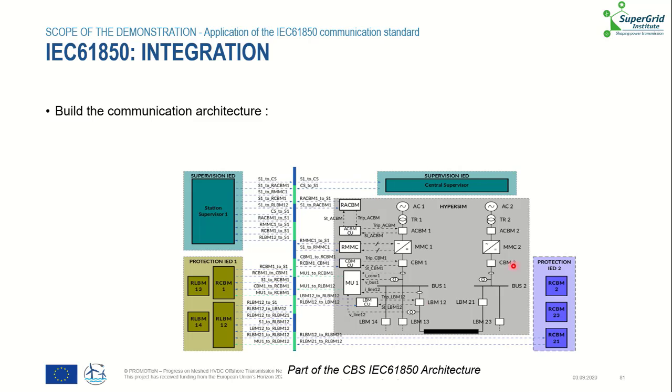Here we have the communication of only a part of the converter breaker strategy. As we see, we already have a lot of signals just for one station. Hence, a good naming convention is mandatory to avoid confusion. Also, we need a clear and unique definition of the communication link. By that I mean who is talking to whom. Finally, we need to identify this communication link by an identification process. We use the logical path defined by the norm, and as IEC is an Ethernet protocol, we also use MAC addresses.